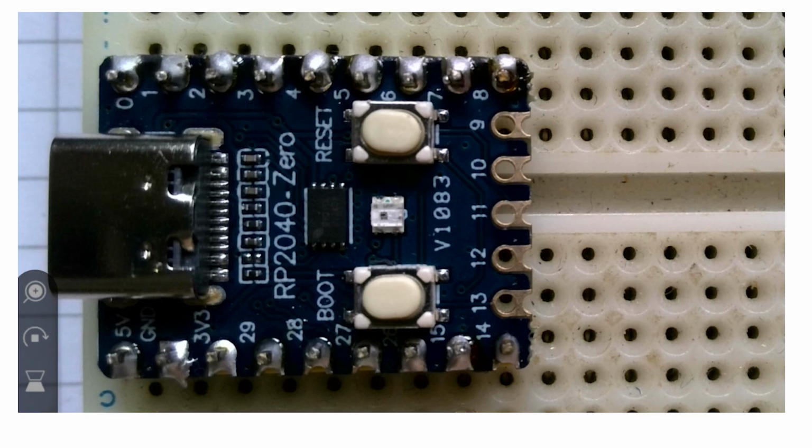But because the RP2040 has got a NeoPixel on it, that NeoPixel is dedicated. It's on line GP16 of the 2040. So I built my circuit and I put the circuit on, let's say, pin 18 of the 2040 to drive whatever it is that I'm driving out in the planet with my NeoPixels.